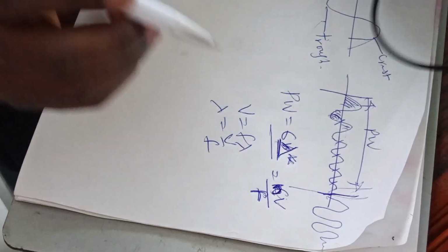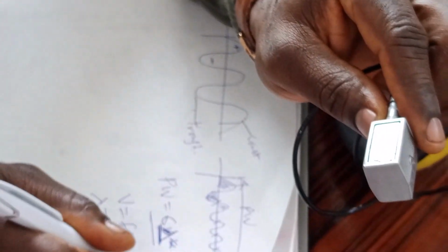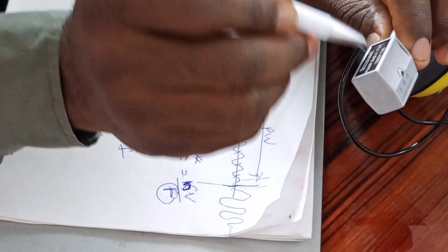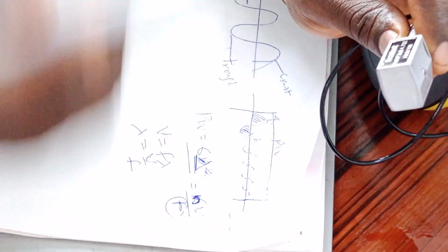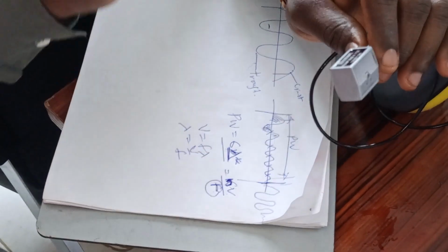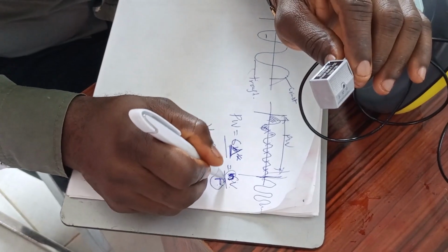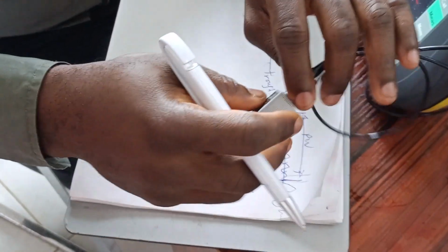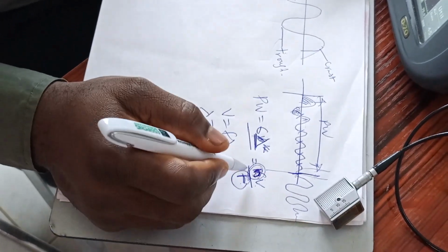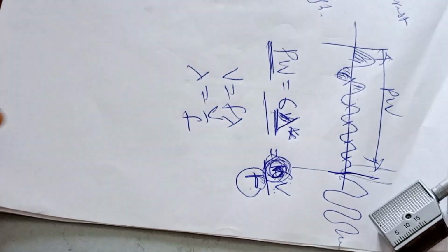But if I pick this probe, I can get the frequency of it, it is normally written on the probe. The velocity of the material I'm used to working with, I can easily get it. So if I know the number of wavelengths, I can get the pulse width.